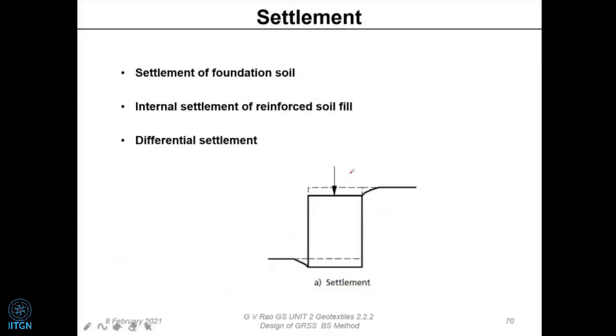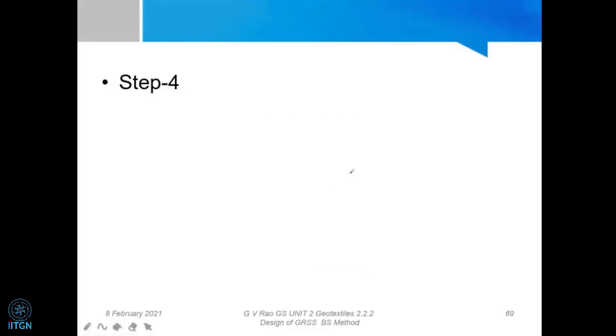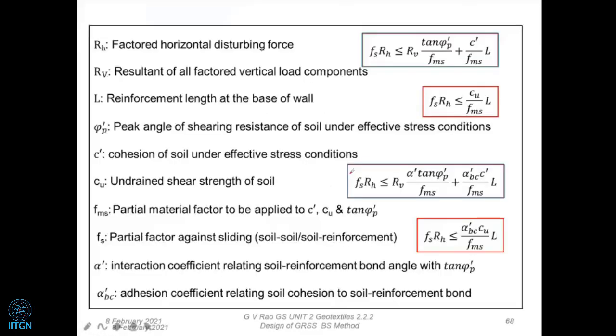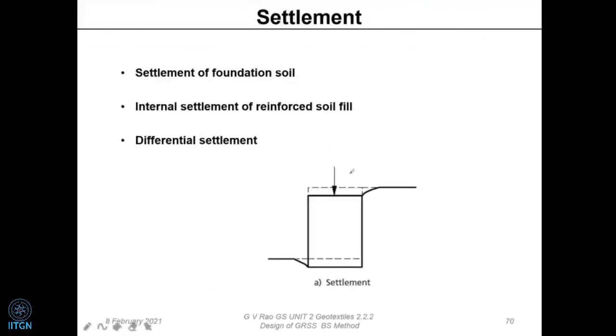After having done this, we can also look at the settlement. One was bearing capacity that we considered. What else did we consider? We also considered sliding along the base. The third thing we are going to do is settlement. Settlement occurs naturally due to the settlement of the base, that means the foundation settling.